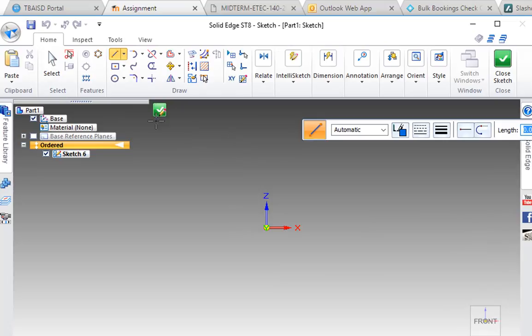So let's do that. I'm going to click on my line tool and snap to the origin. You'll notice that when I move my cursor, that plus sign looking thing, toward the origin where the X, Y, and Z axes all come together, a little symbol comes up that looks like a little popsicle stick, a little gray line with a dot on the end. That means I'm snapping to a point. Once I've clicked and snapped to that point, it anchors one end of the line, and I can move it around. I can pick any angle I want and any length I want.